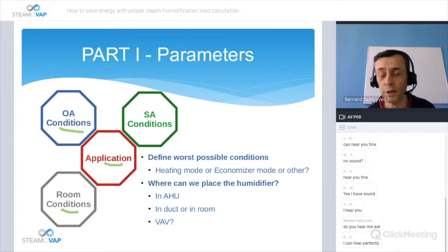A marijuana growing facility, for example, in the early stage of growing needs a lot of humidity, and it's quite hot. So they will need 80 to 85 or 90% relative humidity in the room. And then they have too much humidity during the flowering stage, when the plant is more mature. So then they will have to remove humidity from the grow room.